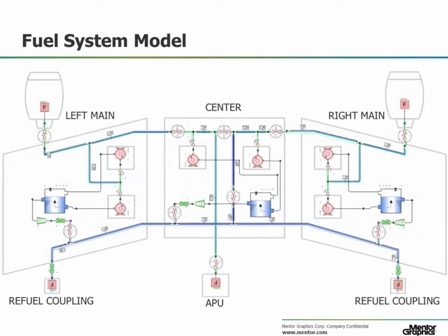Here is a Flowmaster system model drawn directly on top of the schematic image. We've added source components for our boundary conditions, and extra loss components for items like filters and couplings. You'll also notice that the tanks do not take up the whole area outlined in light blue, but instead are single discrete components. The thin link lines represent a direct connection between adjacent components. They're not pipes. Nodes sit in the middle of the links and serve as convenient points to enter elevation data and interrogate flow results of temperature and total pressure.